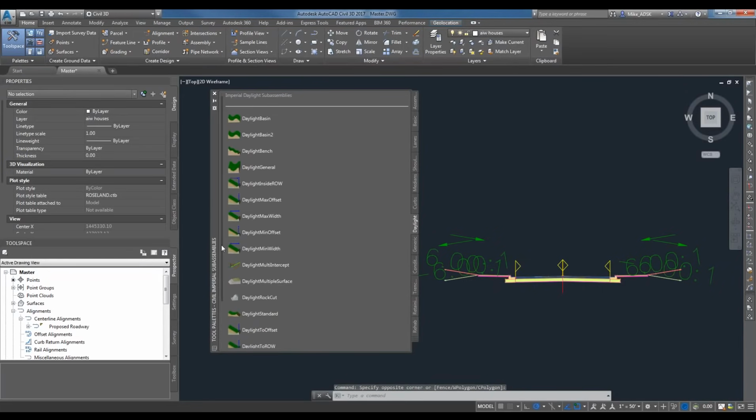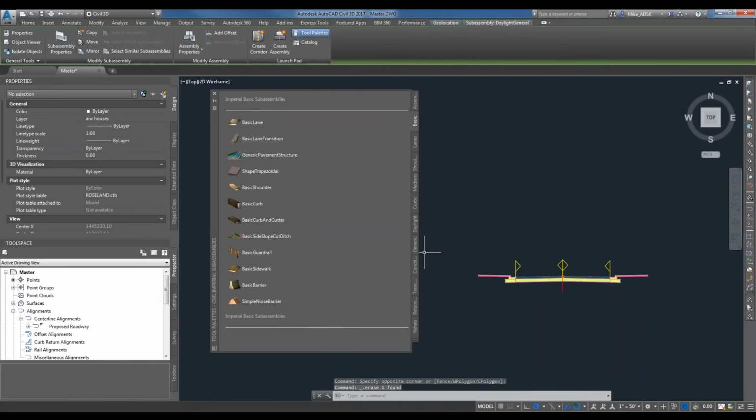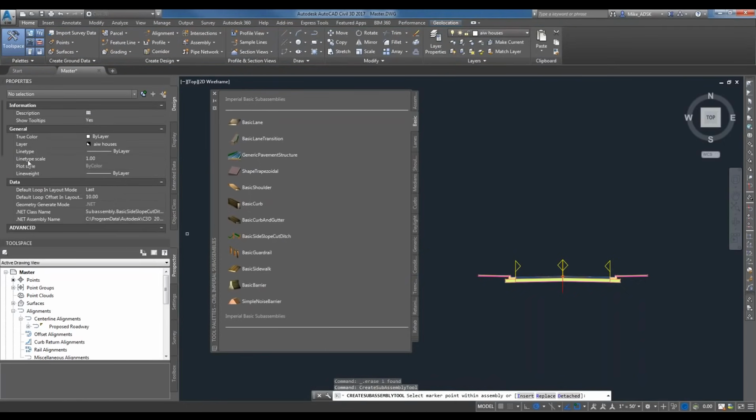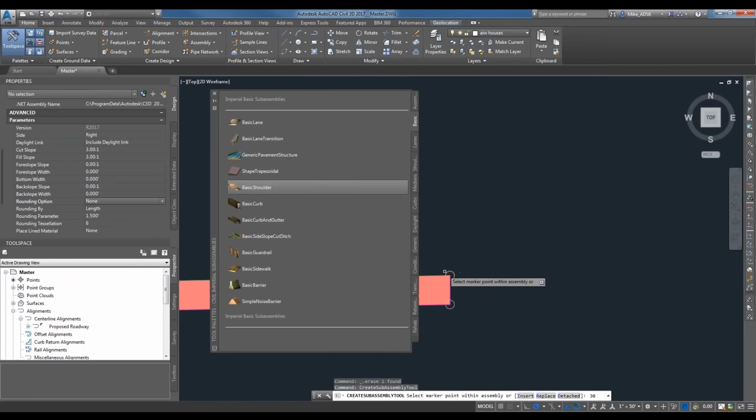So, actually, hold up. Let me make sure that before we continue, because what we're going to do next is we're actually going to create a corridor out of all this. I'm going to delete these guys because these guys are not the ones that I want to be using. I actually want to use this one. This is the guy. Make this 3, make this 3. All these guys is 0. So what this guy will actually do, it'll daylight and then create a ditch for you. 0 everything out. Create that guy in there.